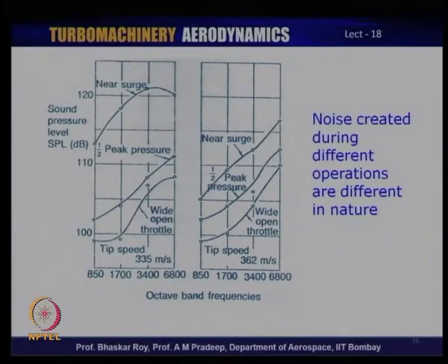When the compressor has gone into surge, which is the worst situation from stall, the noise is much higher, and in fact, an experienced compressor operator can make out that the compressor has indeed gone into stall or surge by hearing the noise coming out of it. So, noise is easily identifiable when the compressor is surged. It depends on the tip speed.